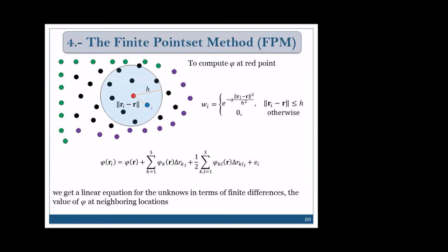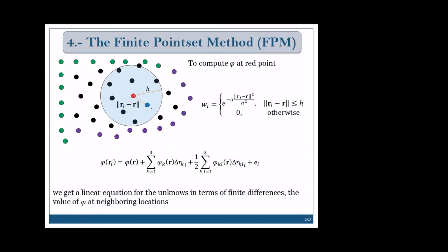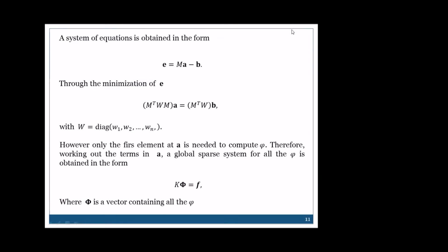Then with these n plus 1 equations, we can go to the truncation error, that is the property that we want to minimize in this step. So this equation contains in the matrix M these spatial finite differences from the interpolation equations, but also one row in this equation contains this constraint of the pressure Poisson equation. So when we minimize this truncation error, we take into account the interpolation between the particles, but also the constraint of the pressure Poisson equation. So this is the idea.